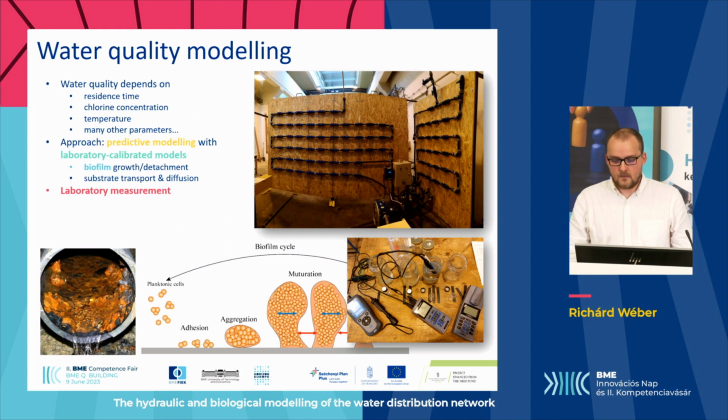And with this measurement equipment, we would like to calibrate the mathematical models, and then with the correct parameters, we can introduce these mathematical models to the hydraulic solver, and that can predict the sensitive areas in the water distribution network.